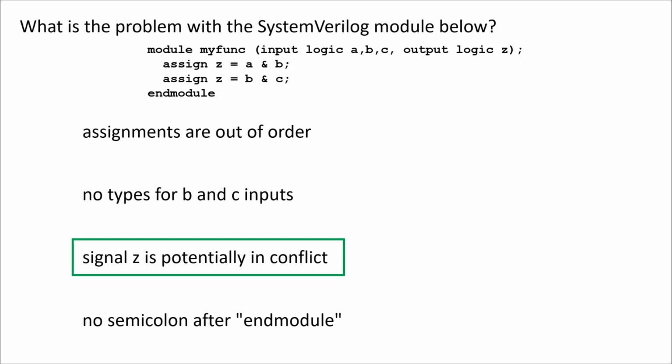X is really just for simulation purposes, whereas Z is a real concept. Z is something you could actually set in real hardware, because Z means don't pull it up, don't pull it down, just let it float. That's Z. And then 0 or 1, of course, is either ground or VDD.